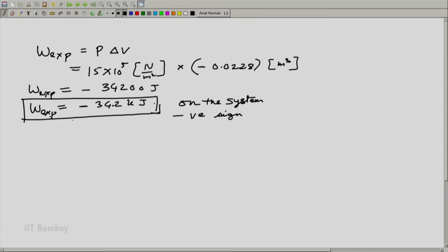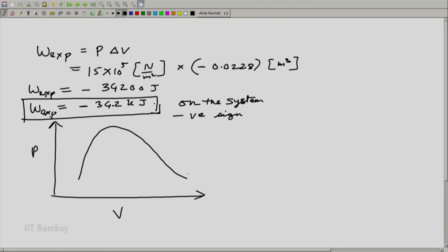What we can do also is to show the schematic of this on a PV diagram. If I want to show on a PV diagram now, alright, this is my state 1A, this is line of 15 bar. So, this is 1A, which is maintained at saturated liquid and at 15 bar. 1B we have found that it is a superheated region.